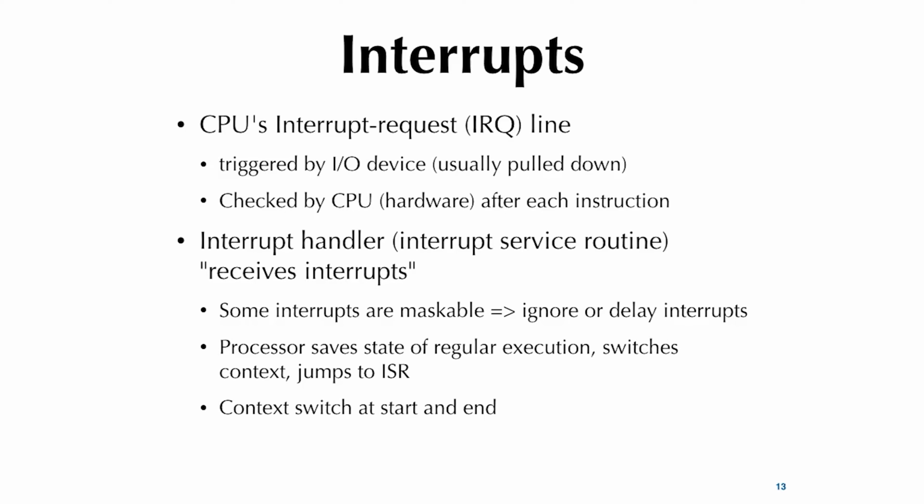So interrupt, oftentimes what happens is you view this as having made some interrupt requests, or IRQ. IRQ is a very common term, especially in PCs. A lot of times in older PCs, you see an error message: oh, this IRQ conflicts with some other IRQ. What is IRQ? It's an interrupt request, that's what it is. On devices, it might not be called IRQ, it might be called data ready, it might be called something else. But basically it is a line, a signal generated by the peripheral device to notify the processor.